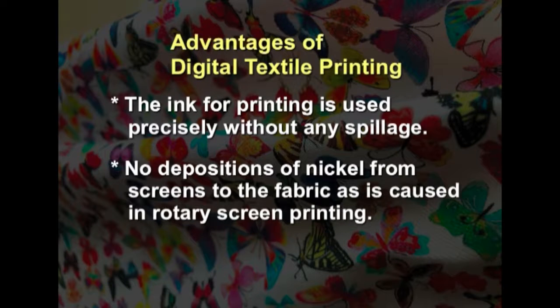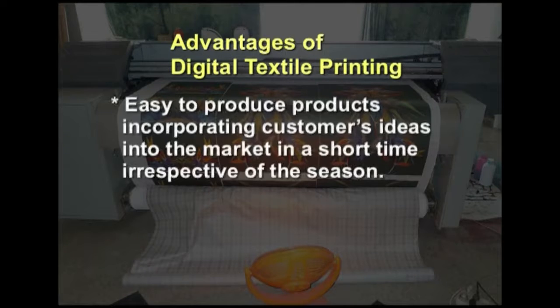And there is no deposition of nickel from screens onto the fabric, as is caused in rotary screen printing. Digital printing is applicable to a wide range of fabrics, unlike the rotary screen and screen printing methods. It is easy to produce products incorporating customers' ideas into the market in a short time, irrespective of the season.